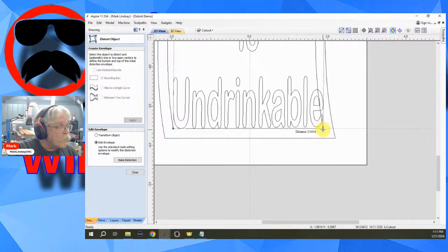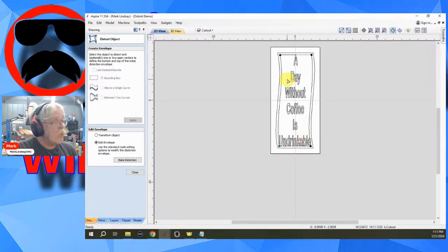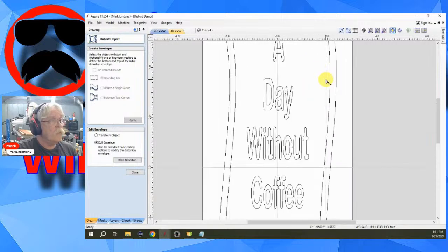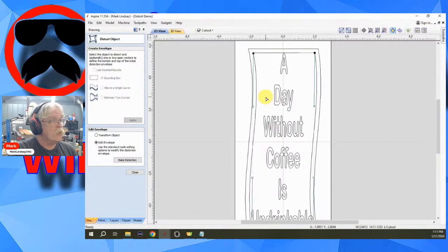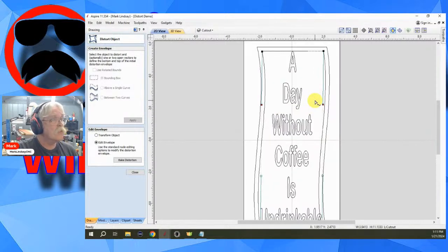You can do it. Snap it to that corner. There we go. Now I'm going to cheat. Right click to Bezier. Right click to Bezier. Now I have just changed these two vectors to Bezier curves because now I need to distort my text to match this wavy shape. So I'll select both of these nodes.